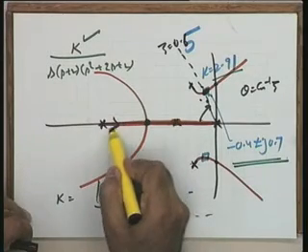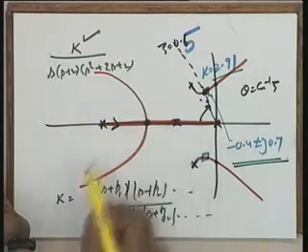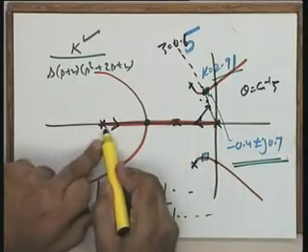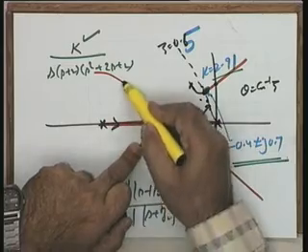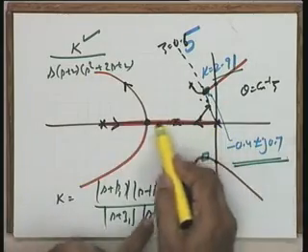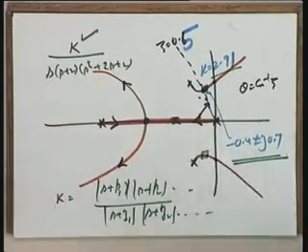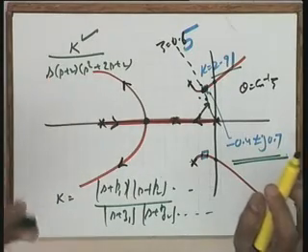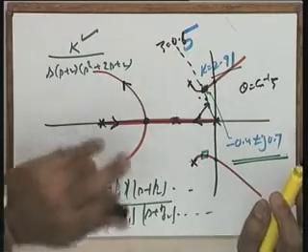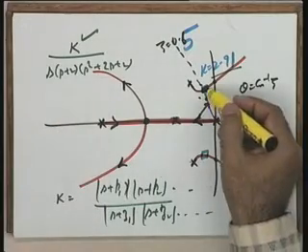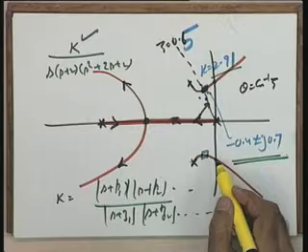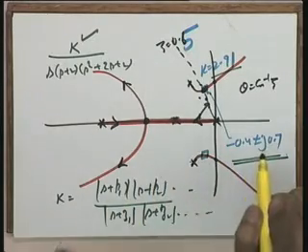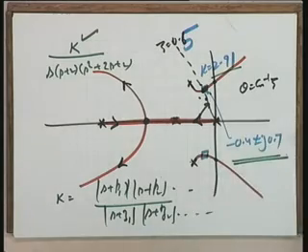Please see, one of the root locus branches is going to start this way. The other root locus branch is going to start this way. So as k increases, one root locus branch is going this way, and as k increases, the fourth root locus branch is going this way. So it means you want 2 points on these two root locus branches which correspond to k equal to 2.91, because k equal to 2.91 is the value of interest to you. So now you think of the procedure.